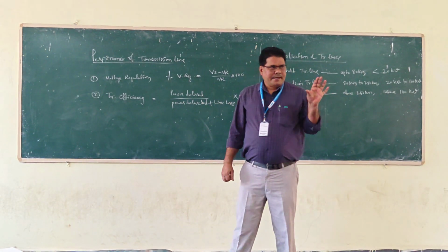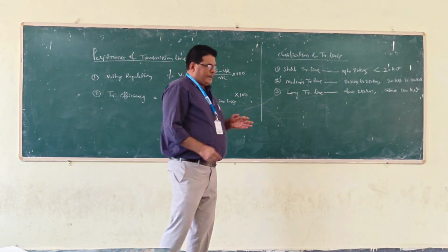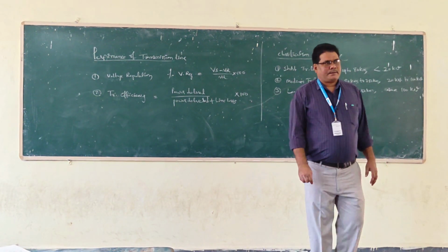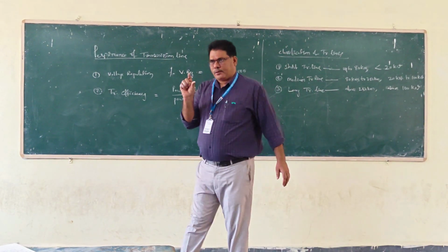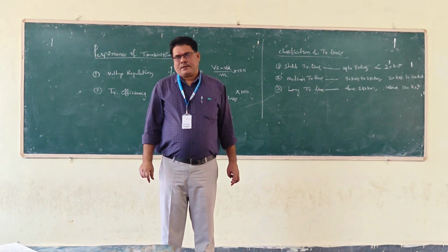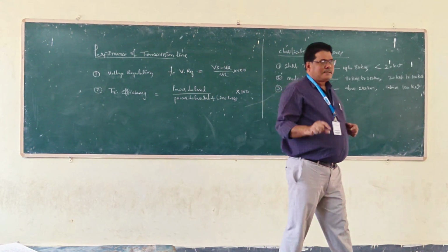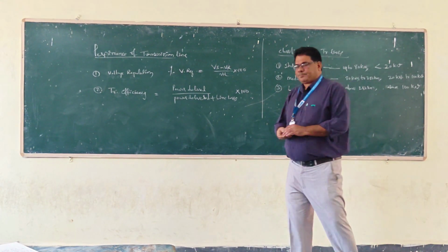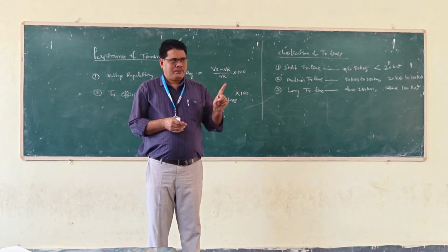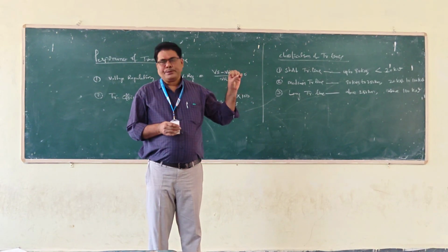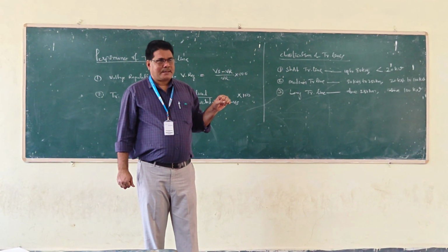Their length is up to 80 kilometers, and the operating voltage is low, 20 kV. Due to the insufficient length and the very low operating voltage, the distance is comparatively low, 80 kilometers. So the effect of the line charging current, the capacitive charging current, is very low.